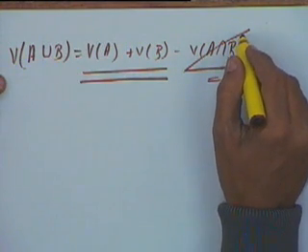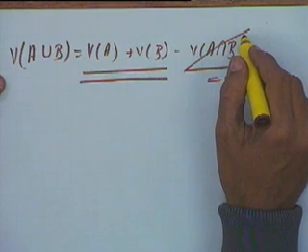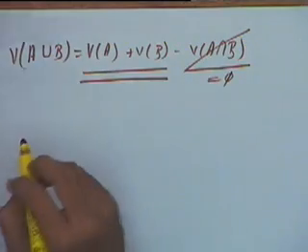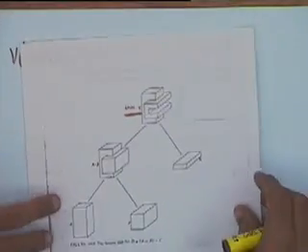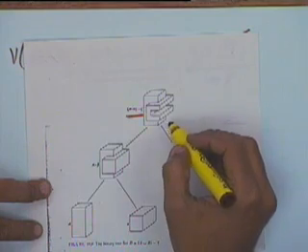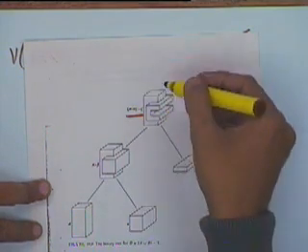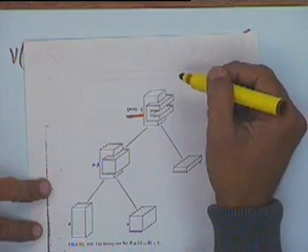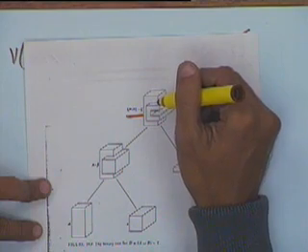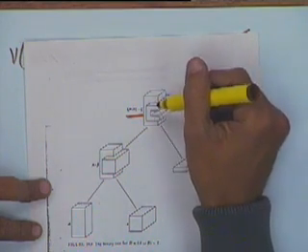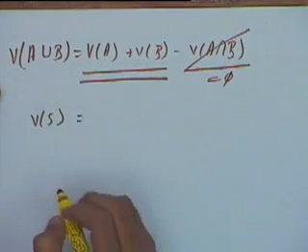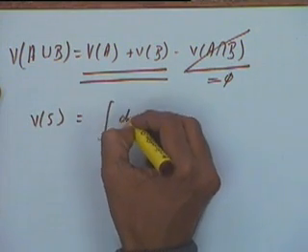But if that does not happen, then we have to use the boundary representation of the solid. If we have any arbitrary solid, let us say this solid, and we have its boundary representation, we have the equations of all its faces and the interaction with the other faces and so on. We can use that representation to get the volume of the solid. How we can do that? See, the volume of a solid is a volume integral of dV.